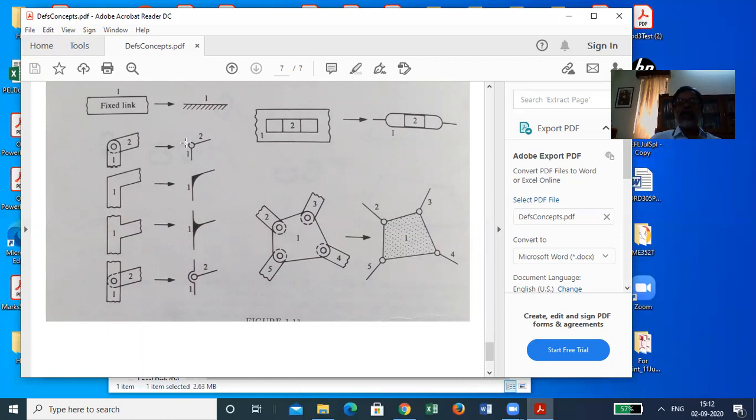You do not put this little round thing because it will actually show a revolute joint. But if you simply make this and this, okay, then you would be creating a confusion of this revolute pair being there and you not showing it by mistake or by slip. To indicate that it's not a slip, it's a part of a single link, you fillet this region. Okay, and that makes it a rigid body in depiction completely.